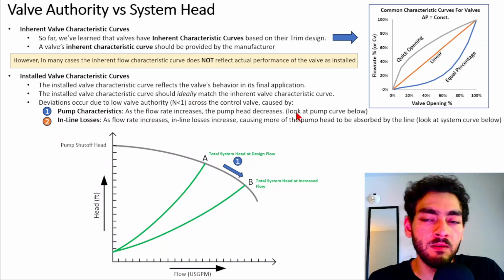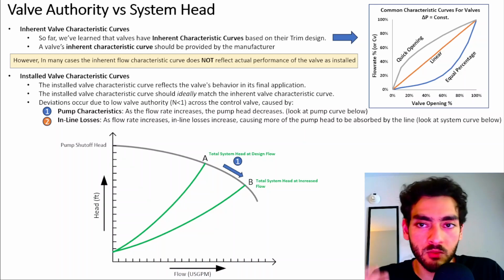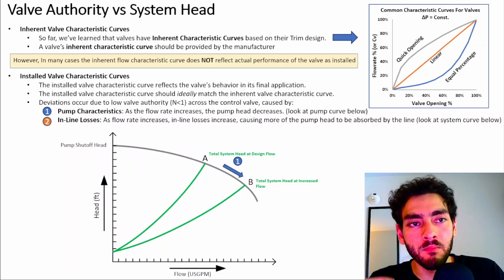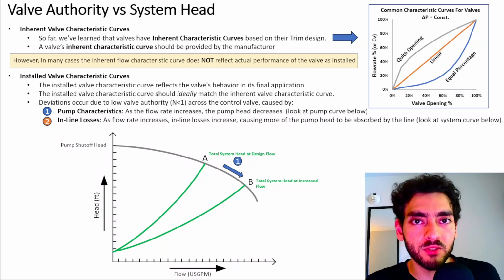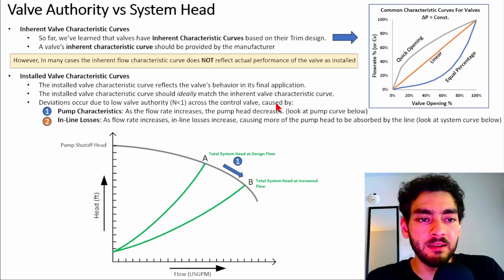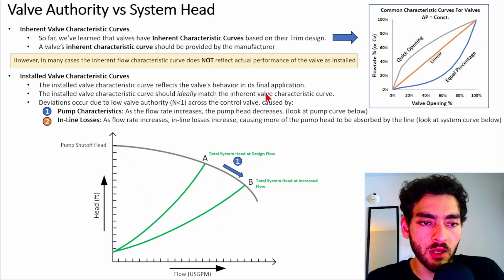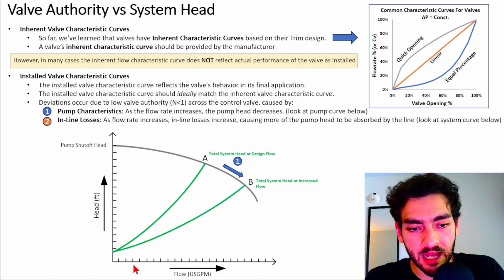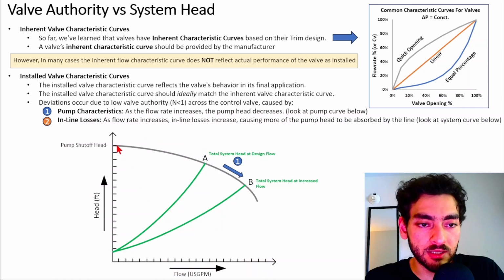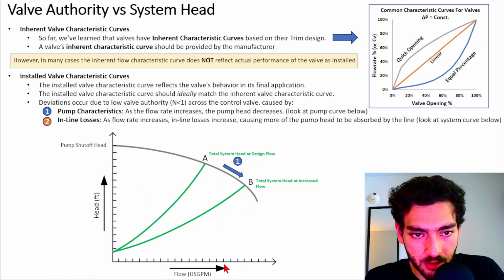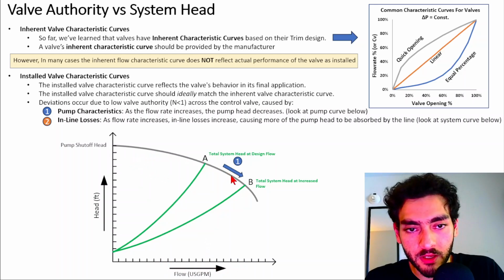So in this course, we're talking about pump sizing and we're talking about transporting liquid. And in most applications, when you're transporting liquid from one point to another, you're using pumps to do that. And so in piping configurations, you're mostly dealing with pumps, and each pump has a characteristic curve. So if you look at an example, such as a centrifugal pump, we've talked about pump curves, and here's an example of a pump curve for a centrifugal pump. You could see that as the flow rate increases on the x-axis, the pump curve decreases.